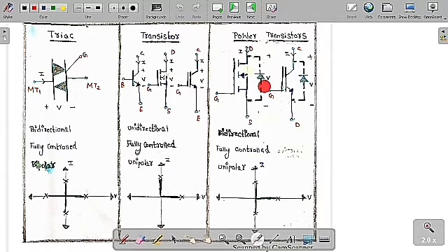The internal diode is going to conduct, and we are going to get a voltage of zero but a current of non-zero. So we can say it can only block a positive polarity, but not the reverse polarity. Here the current passes both ways, and only a unipolar voltage is blocked. So it is called a unipolar and bidirectional, fully controlled switch.